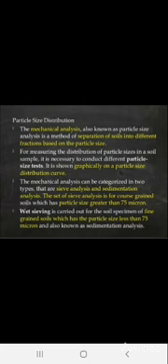So the mechanical analysis, also known as particle size analysis, is the method of separation of soil into different fractions based on the particle size, right? For measuring the distribution of the particle size in the soil sample, it is necessary to conduct different particle size tests. It is shown graphically on the particle size distribution graph. So the main point is that it is graphically represented. Whenever you find the numerical values, after that you draw the graph, where on the x-axis we show the size distribution, and the percentage finer we show on the y-axis.